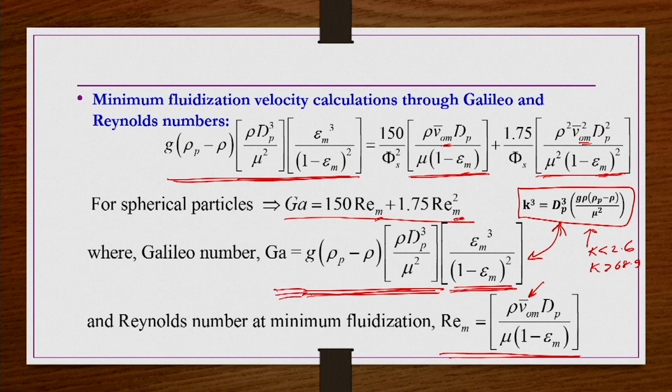So, we cannot say that below this Reynolds number it is laminar flow. Some people say REP less than 1 is a kind of laminar flow for packed bed, but even some researchers argue that up to REP 5 to 10 also the bed remains in laminar flow conditions. So, those kinds of ambiguities are there. That is the reason we cannot have corresponding limit numbers for the Galileo number for these conditions, though by mathematical appearance K and G appear similar.